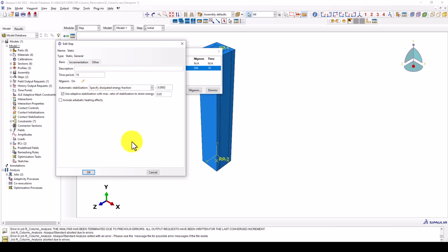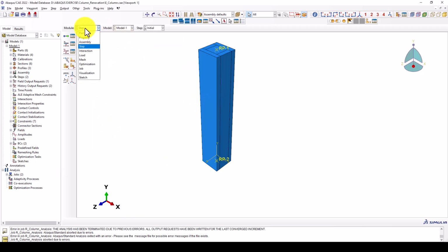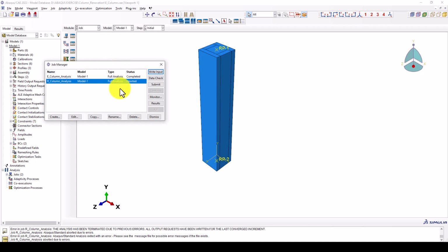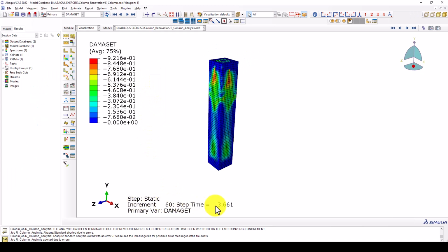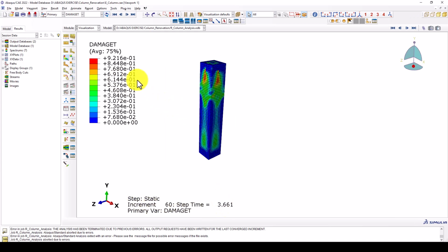And also another solution is to reduce the connectivity of the elements, and that also impacts the convergence and the solution. But because the deformation is quite large, in each attempt we cannot converge, so the analysis is challenging and needs to stop.